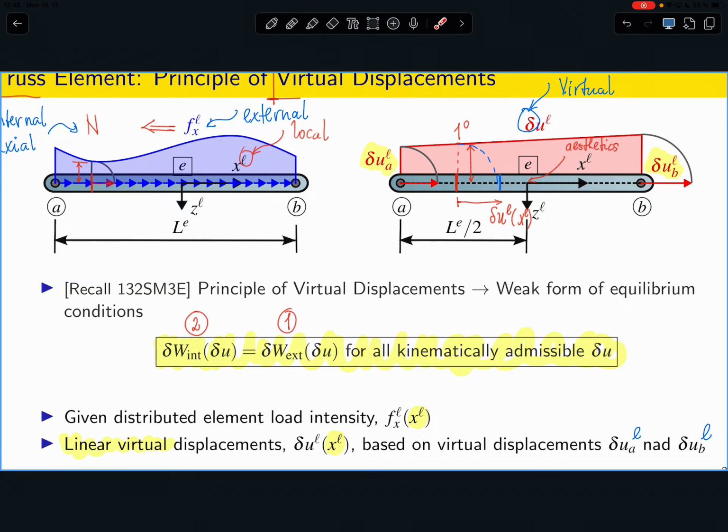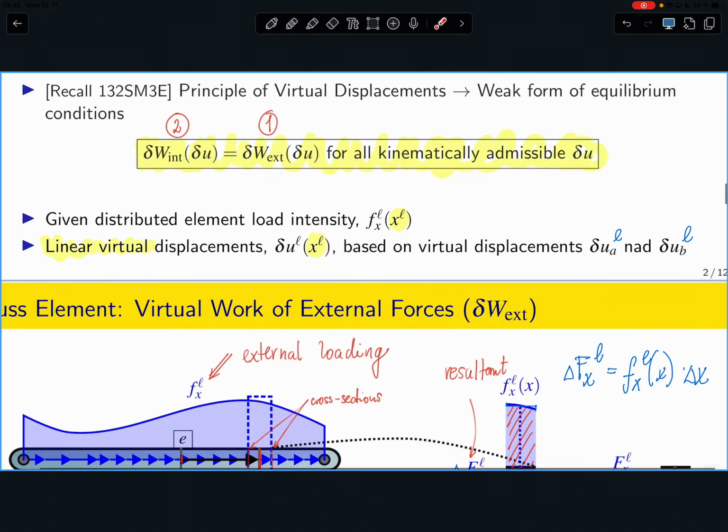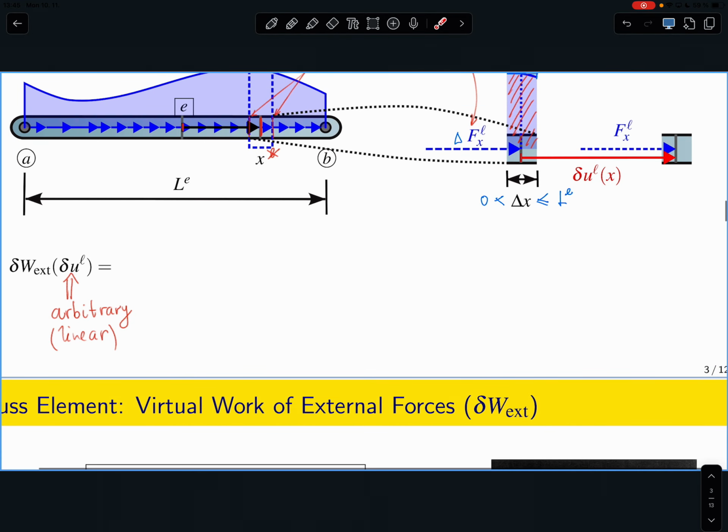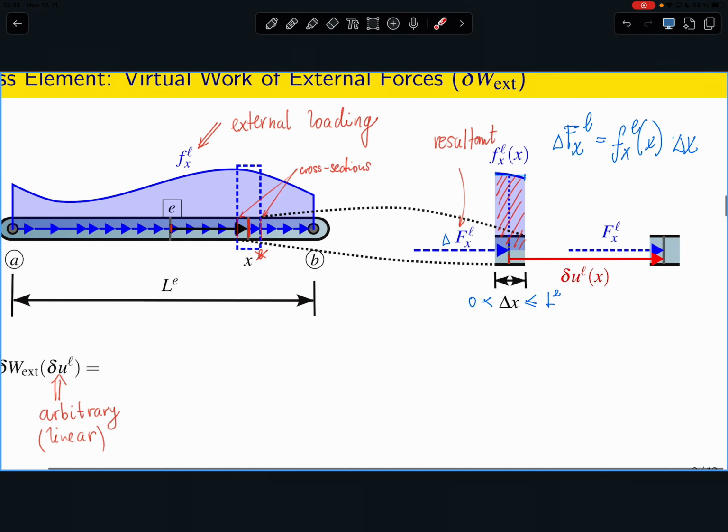It would give me delta UA and delta UB. By that construction which I discussed, I can take the value delta UL which I see there, and it tells me that this small piece of the truss moved by this amount as a rigid body, because this delta x is very, very small, so I can assume that it does not deform substantially.